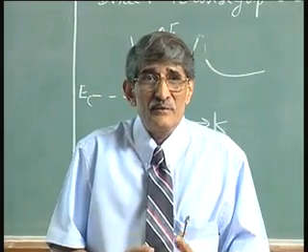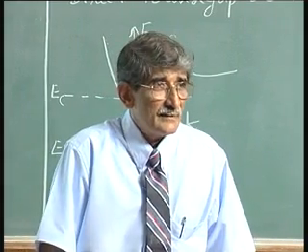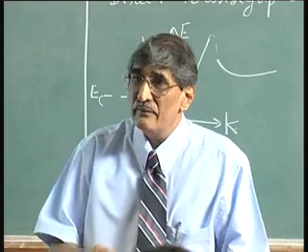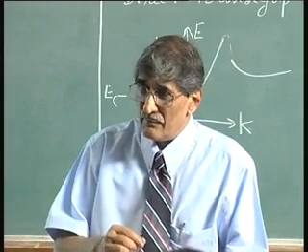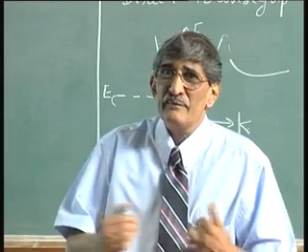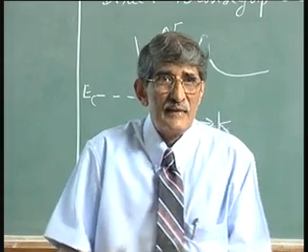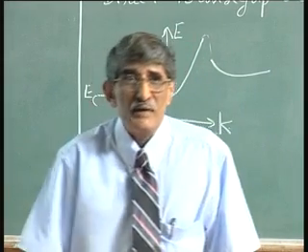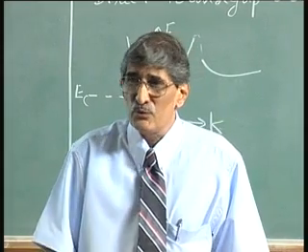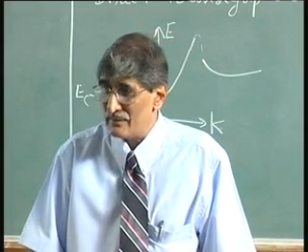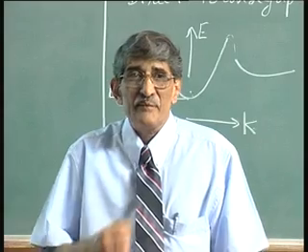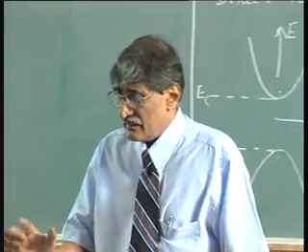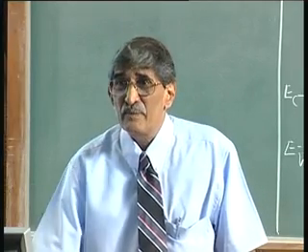So, the nice thing about this is you can mix gallium and aluminum with arsenic and vary the band gap from 1.43 to 2.2. You can vary the band gap from a direct band gap to an indirect band gap. That is total engineering, band gap engineering. People always love to use new terminologies. The band gap can be engineered by mixing the materials. More about these things I will discuss. The entire picture I will bring back.